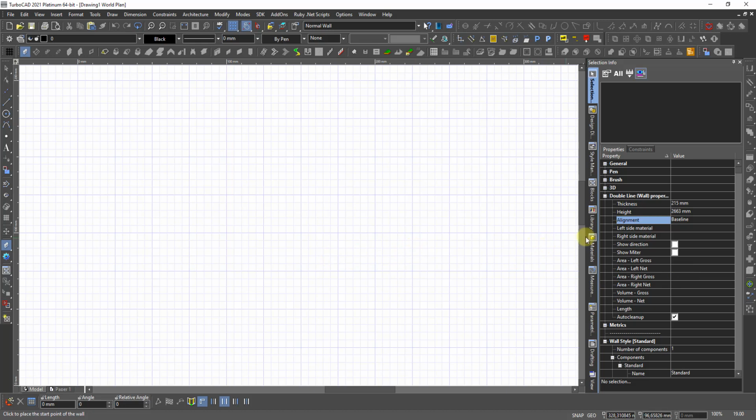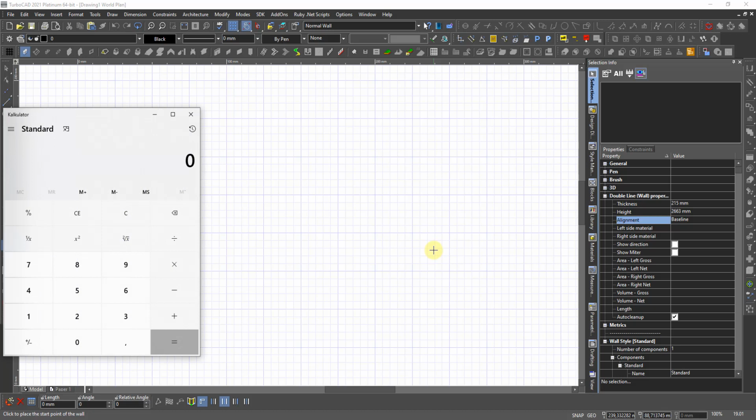Maybe it was in the video the day before yesterday, I switched the old wall to 215 from 148, and that is 148 plus 13mm plate inside, plus 12 plate outside, plus 23 air gap outside, plus 19 cladding, 250. So then I do it just one more time here, so I know why I use 250.